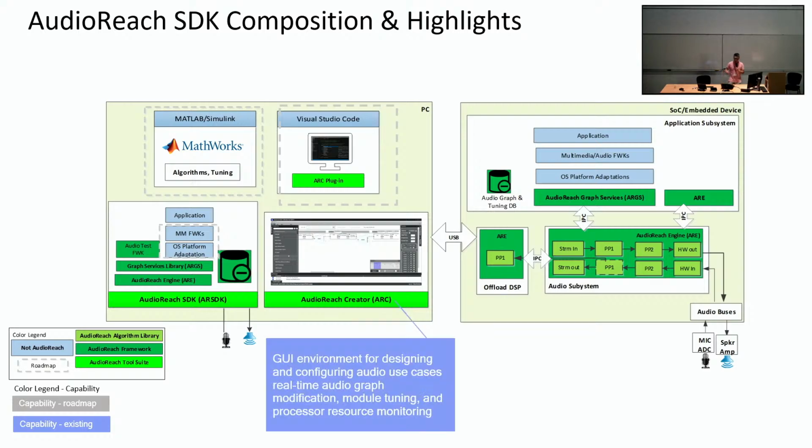Okay, so now let's get into the Audio Reach SDK composition. The very first thing, starting from the embedded PC, is Audio Reach Creator. This is a one-stop tool providing a GUI environment for the use case designer to design use cases by dragging and dropping different processing modules to form your use case graph. Along with the use case graph, you'll be able to configure all the modules that are linked in your use case graph.